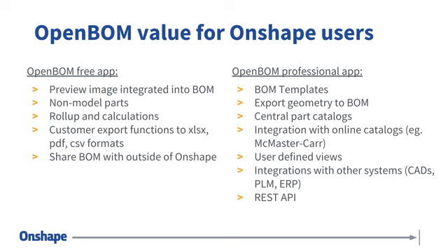You can add non-model parts. So the glue, grease, documentation, anything that you think about, not necessarily should be modeled in Onshape, and you can put directly to the BOM, simplify a lot of things that you might think about bill of material management.